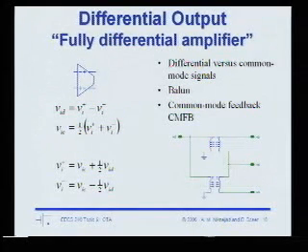And what's a simple way of converting a single-ended signal to differential? Right? Diff pair, right? If I ground the input of one diff pair and drive the other, the output's a pretty good differential signal, right? And vice versa, how about if I want to take a differential signal and make it single-ended?